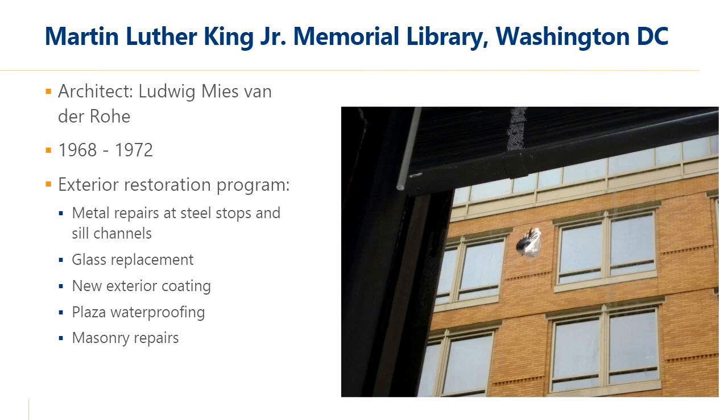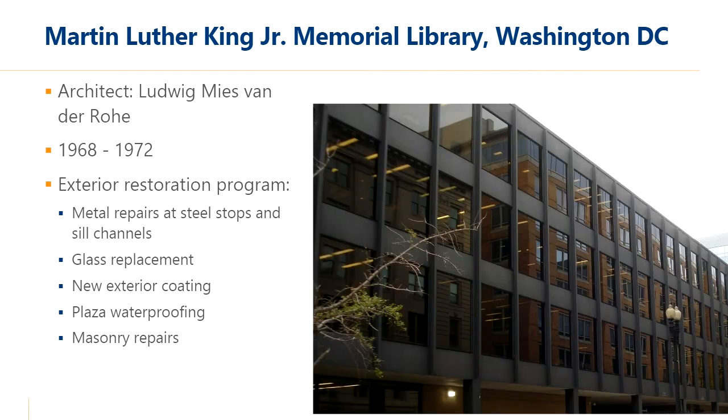Along with human impact, this resulted in glass breakage over the years, and as glass broke, DCPL would install new glass of the same thickness to finish the repair. This had resulted in a mix of original glass and heat-treated units, which were visibly different, particularly in the bronze lights, and especially when viewing reflections of adjacent buildings.